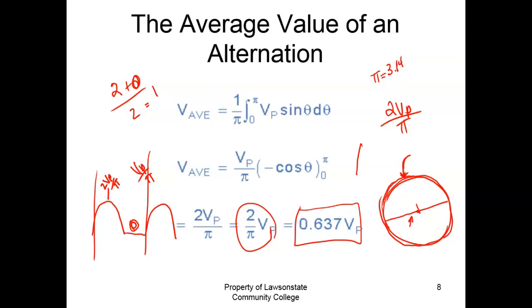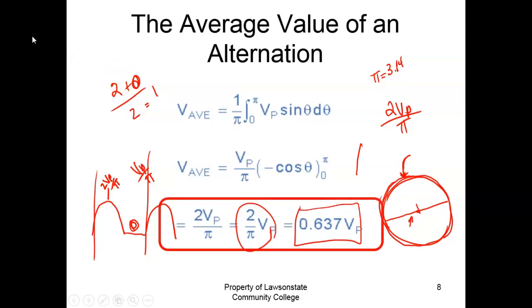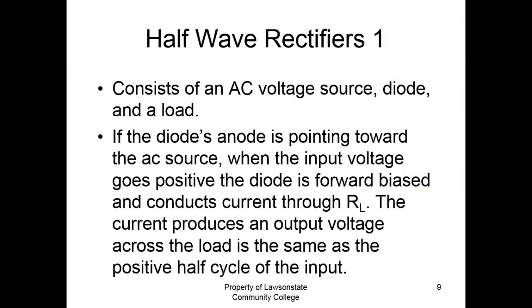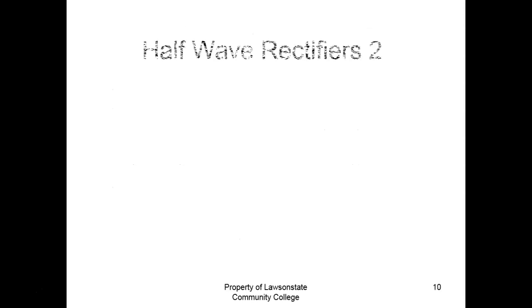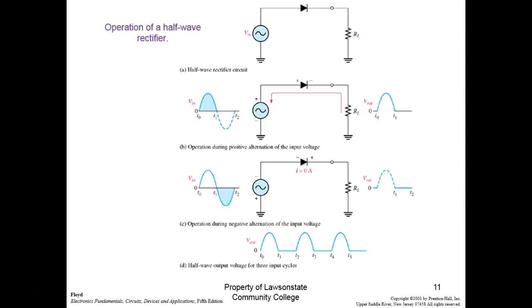So we'll hook this circuit up. And maybe I can get my camera going again so we can actually look at this on the oscilloscope. If not, we'll just come up here and look at it. So all I have to do to make a half-wave rectifier, guys, is this. This is all there is to a half-wave rectifier. So all we have is this guy right here. That's all there is to it. This right here being the load.